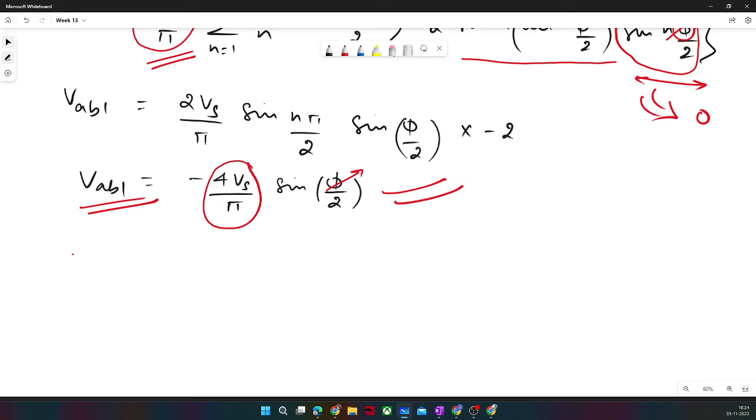But here we are doing it just arithmetically, so it is very simple and elegant. The only drawback is it does not give you much freedom. So first we will see up to what extent we can control with the help of these notches, and then we will move on to sine PWM. So now we will see three-phase inverter control.